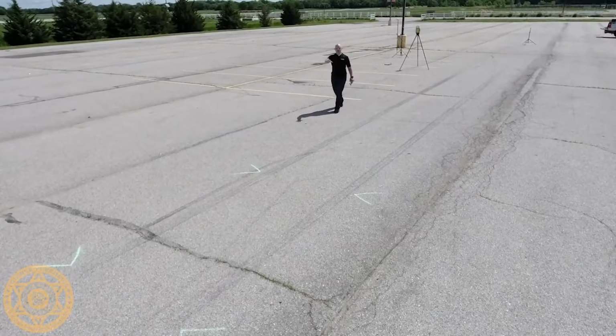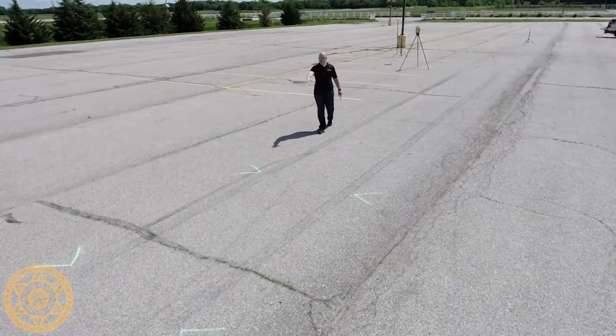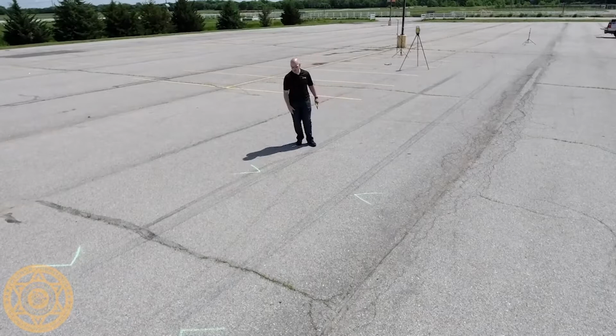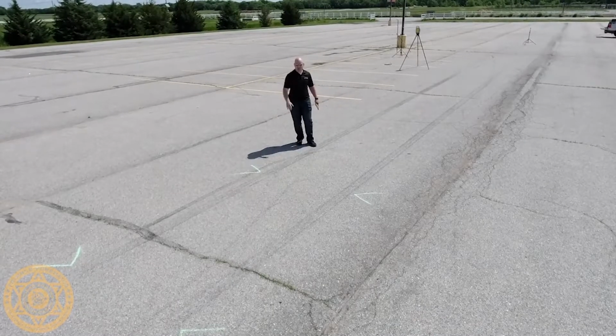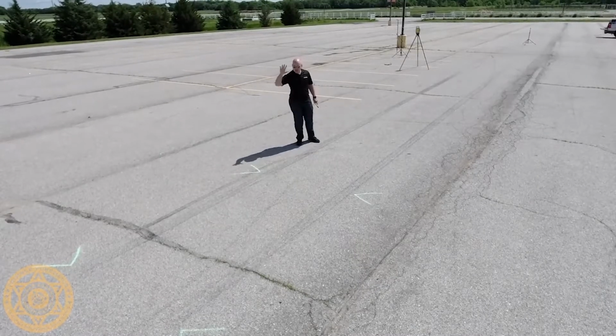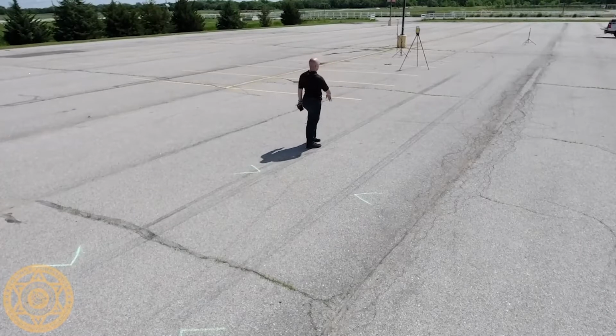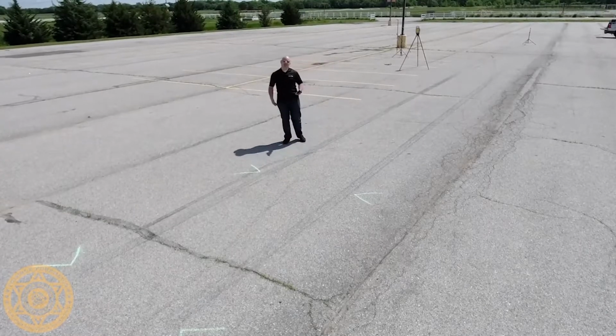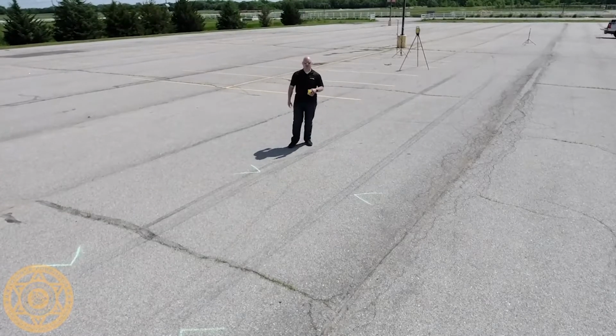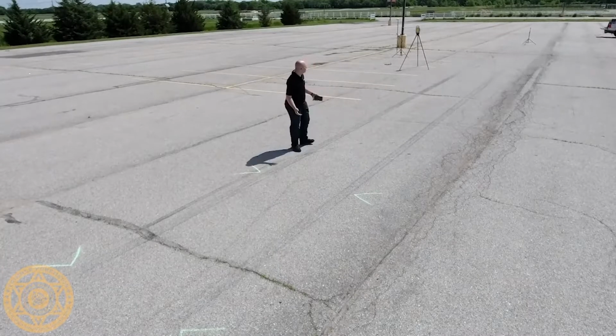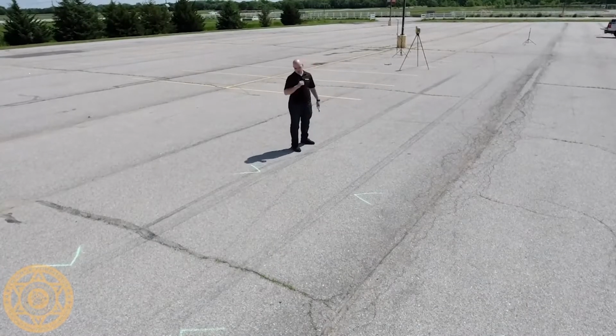This was the final rest for the vehicle at the end of the skids, and I've marked it out in chalk, so we know I was able to move it and we're not cluttering up our scene. What I did here is got up to a certain speed, put it in neutral, turned the key off, and then dynamited the brakes. So these aren't ABS skids, as the trained eye can see. These are just lock-up wheel skids to final rest.